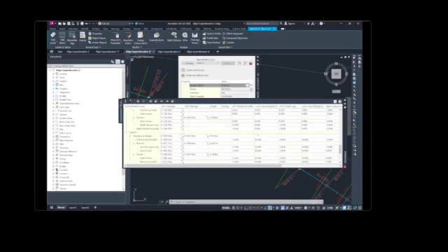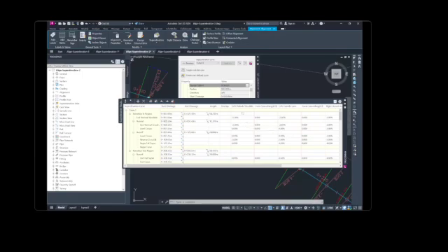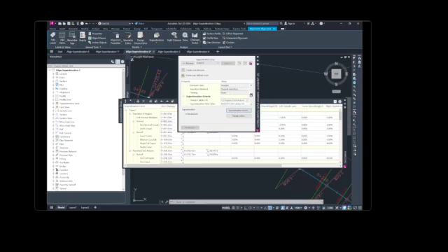In the Superelevation Curve Manager, scroll down to the Superelevation Criteria category, expand the category, and then right-click the Normal Shoulder Width row. The Apply to Entire Alignment option enables you to update the design criteria for a curve, and then quickly apply the change to all curves in the alignment.